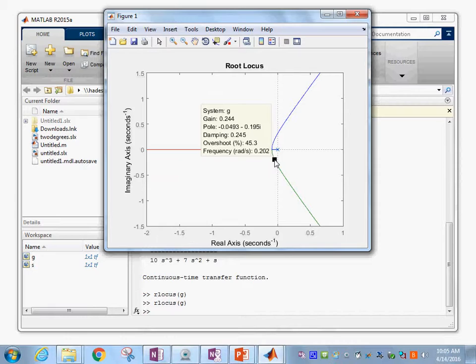Remember, the overshoot is the amount over the settling point that we want, and we could impose on that different restrictions so that we could actually see where we are on our design, or design it for a particular overshoot or things like that. The point is that this is the tool for designing controls.